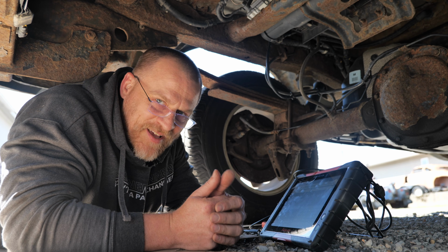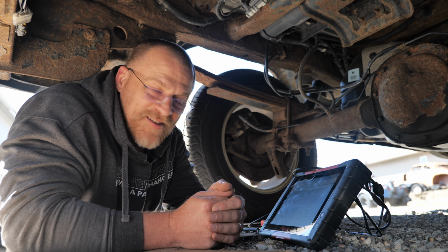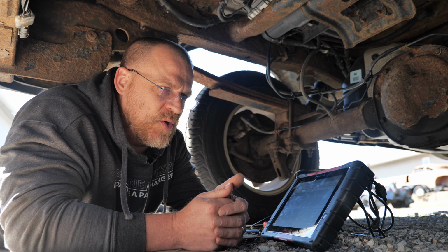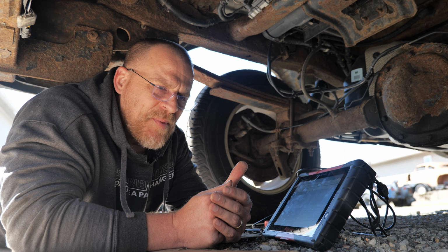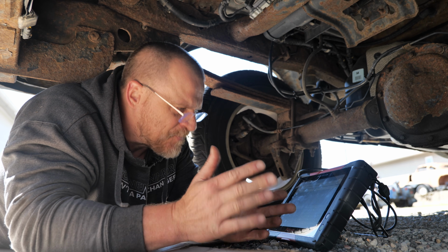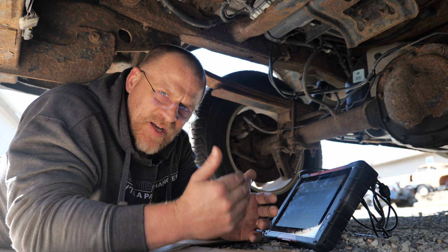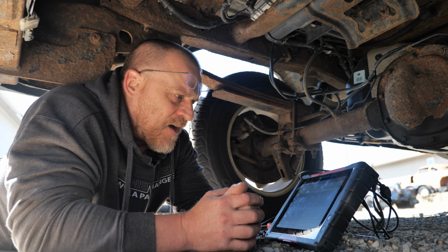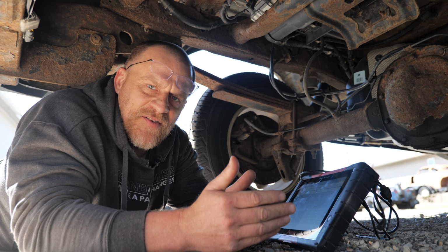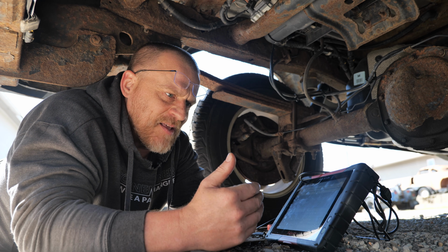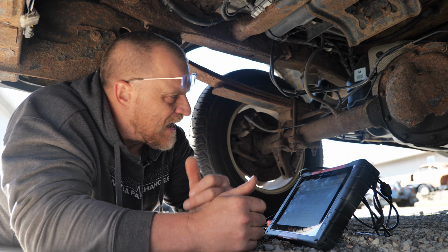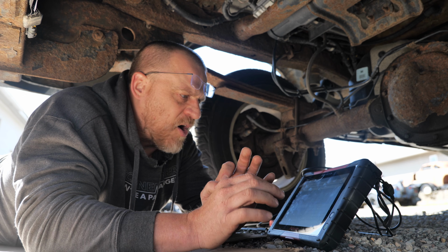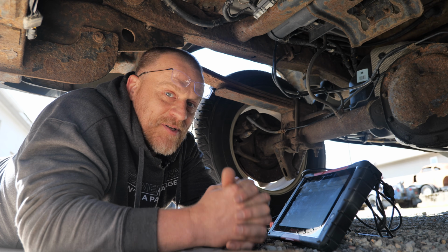I hate to be like, we're done, but we're kind of done. I'm not prepared to make a call. There's no other checks I need to do. Some of you might be thinking, well, what about a power or ground problem back here? It's a good question. The amperage that we saw, that rise in amperage with the command, addresses that problem. The fact that we can get 75 PSI out of this pump, the fact that I can command it to happen and see an amperage rise tells us power and ground back here are fine. At least they're fine right now while we're testing it.